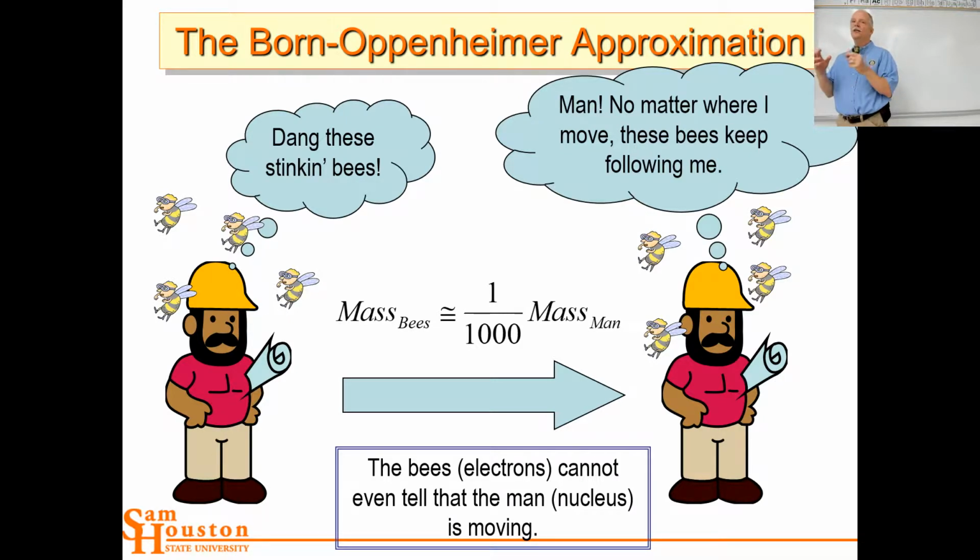So in Gaussian, we can tell the software where the atoms are, and they're fixed in space, and then the calculation determines where the electrons go. It's calculating the electron cloud. That's why another name for these calculations is the electronic structure calculation. And then what it does is it moves the nuclei, and then it redoes the whole calculation. Most of the time you're doing a geometry optimization, where you're moving the nuclei to find the minimum energy so that you can optimize that geometry.